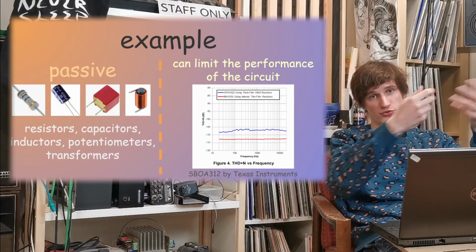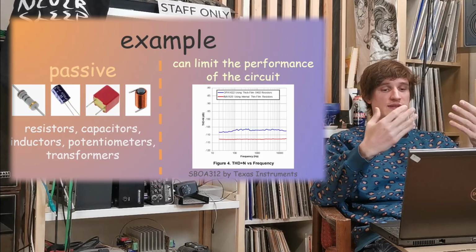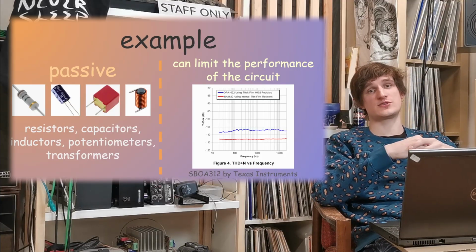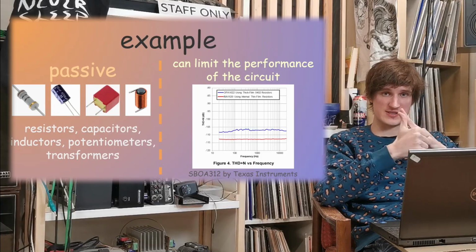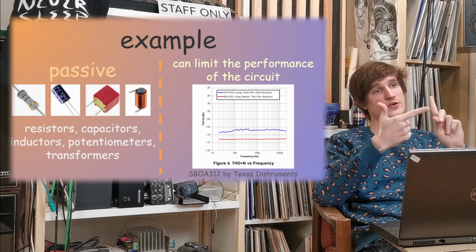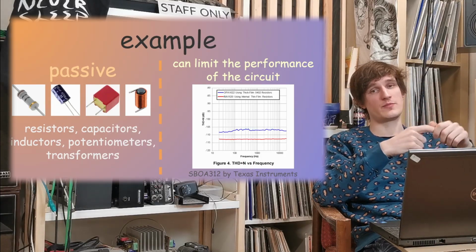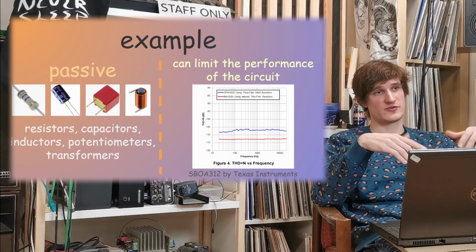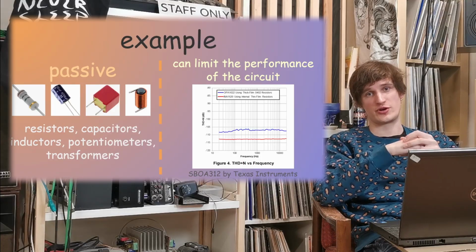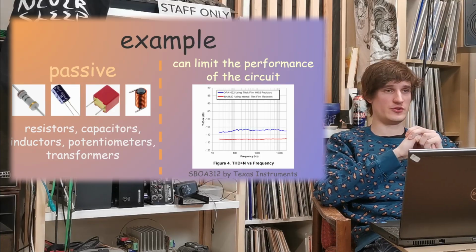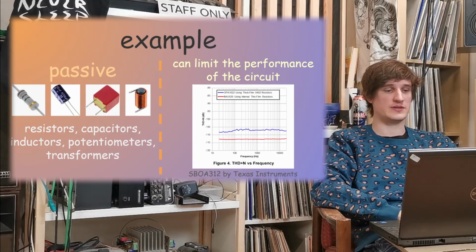Then they took thin film resistors. Those resistors were probably first of all less noisy, and also those resistors were more stable in terms, for example, of temperature coefficient, and I will mention temperature coefficient also a bit later.